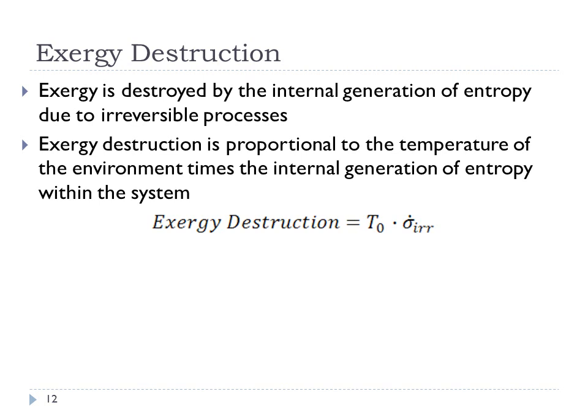Meaning, exergy destruction is relative to what you take as your reference environment. If you take the reference environment to be the cold of outer space, then the exergy destruction is virtually nil. So that's one thing to keep in mind: exergy is always with respect to what you take to be the reference environment.